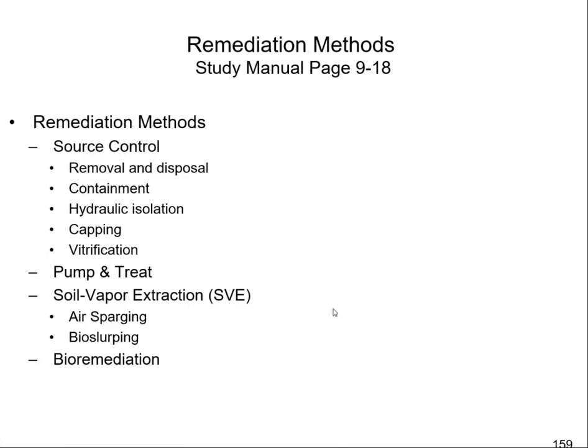And then we have another table in the study manual that elaborates on this information. And these are some of the common remediation methods. So SVE methods, the air sparging and bioslurping, they will sometimes have those terms on the exam. I guess they kind of like those terms, but you don't do SVE methods with DNAPLs because they sink. And this is only for the stuff that's up at the top.